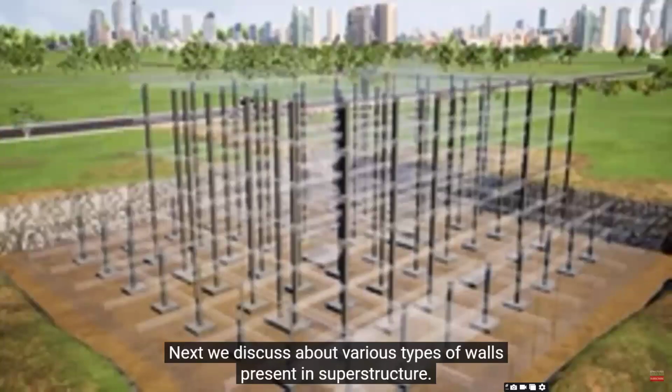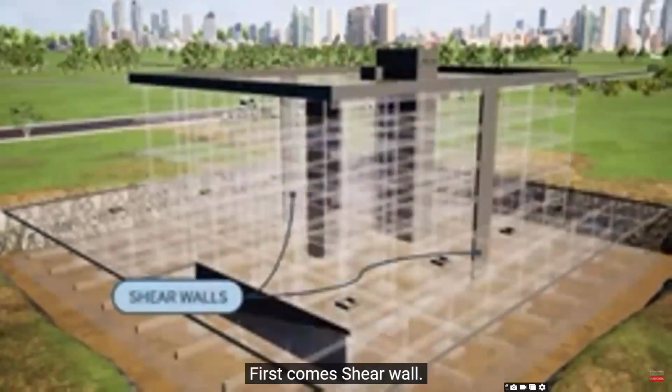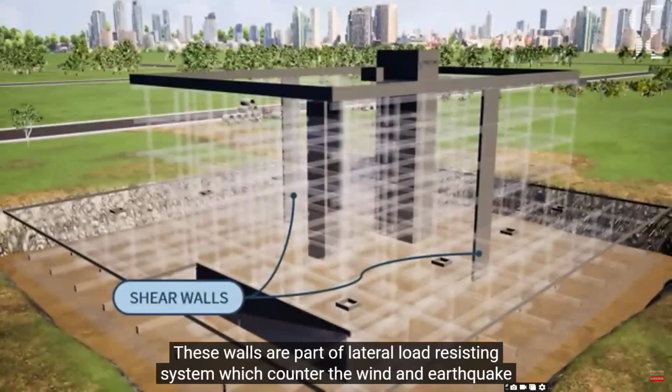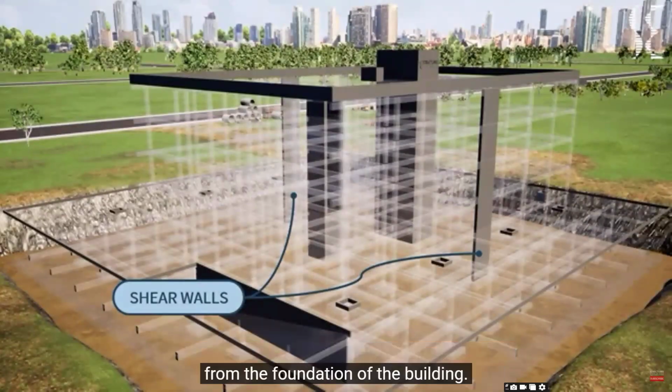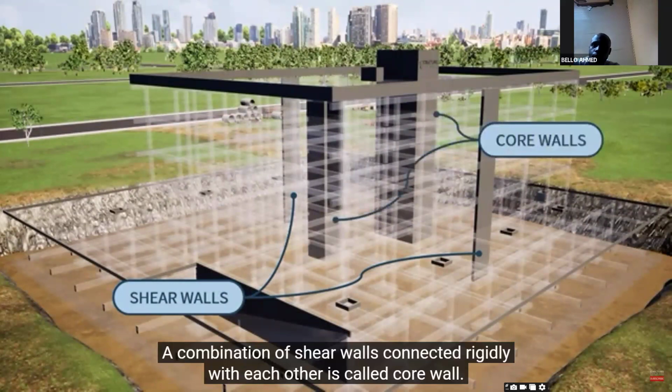Next we discuss various types of walls present in superstructure. First comes shear wall. These walls are part of lateral load resisting systems which counter the wind force and earthquake forces. Shear walls are placed at appropriate locations of the building by design and they start right from the foundation of the building. A combination of shear walls connected rigidly with each other is called a core wall.